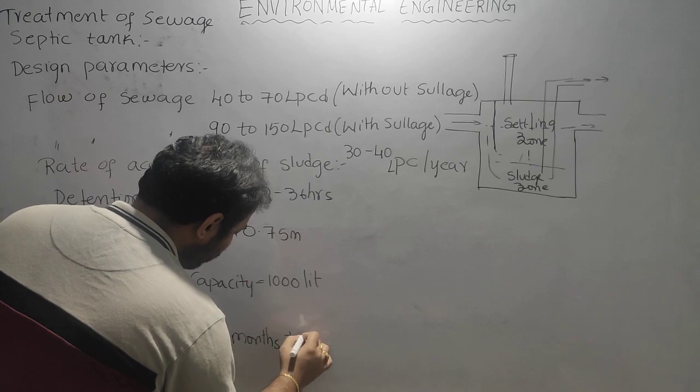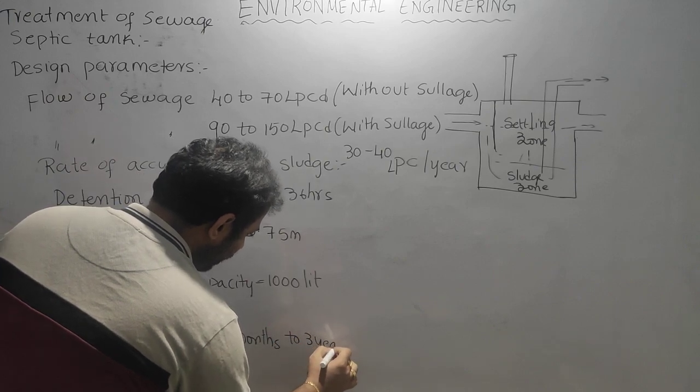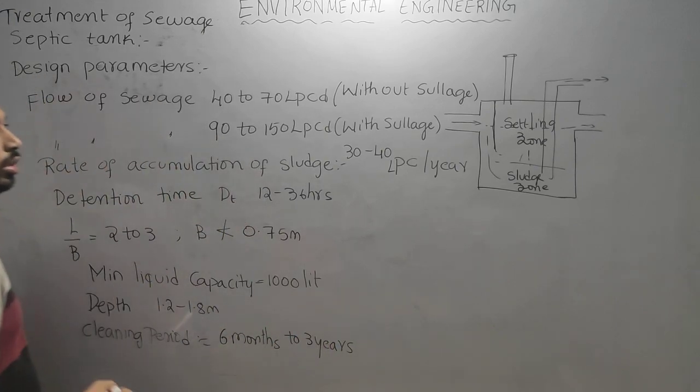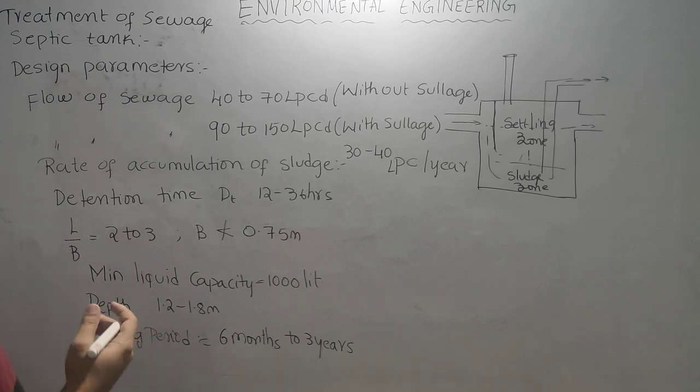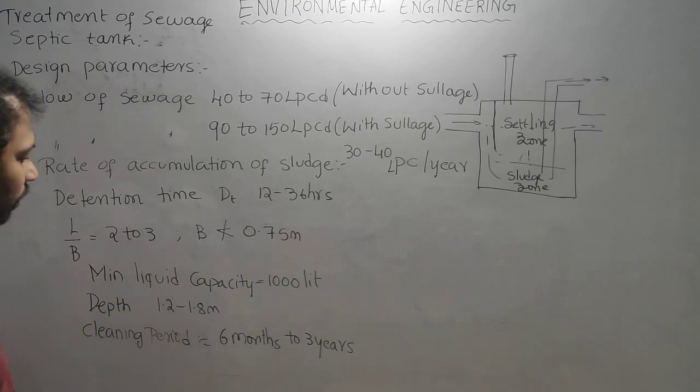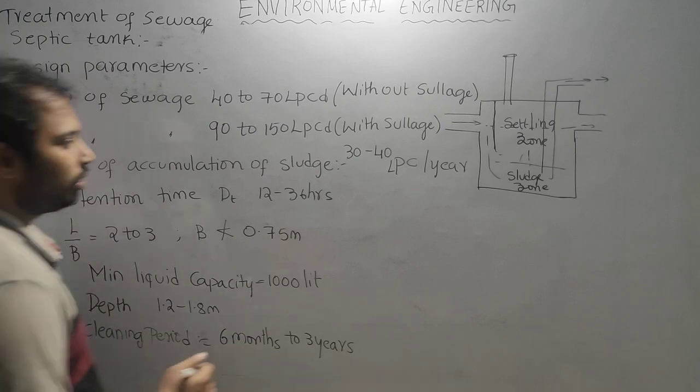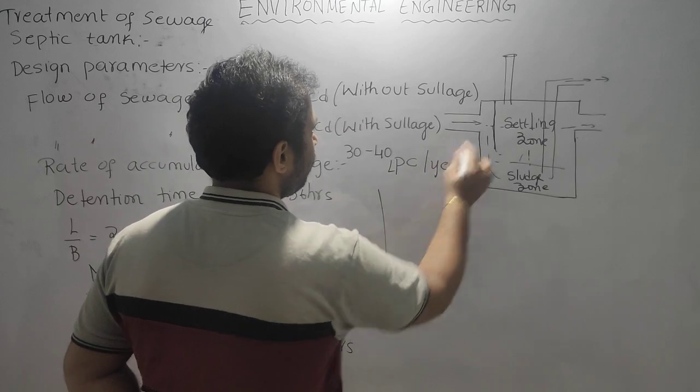It depends upon the size of the tank and how many users are using that tank. Freeboard we use 0.3 meter. So here this is the freeboard.